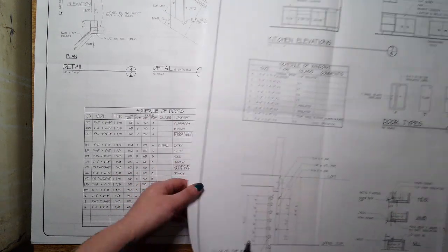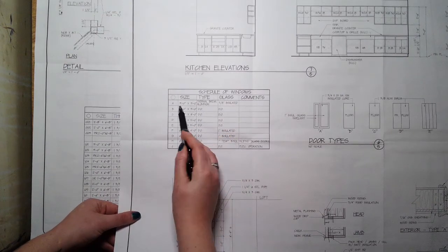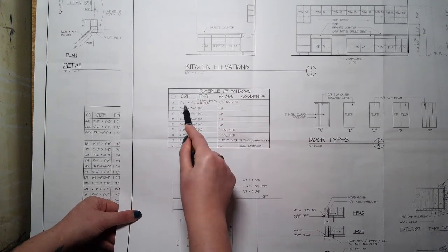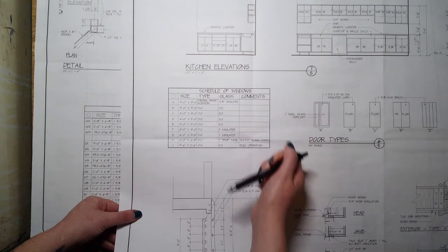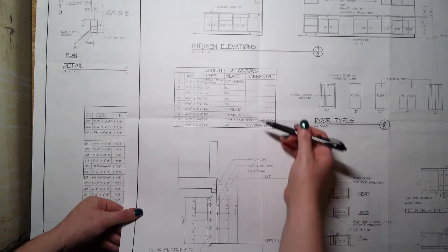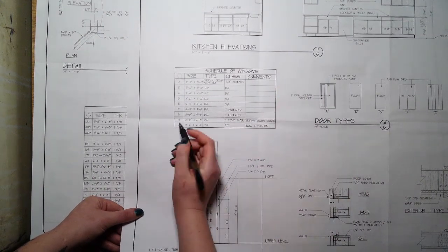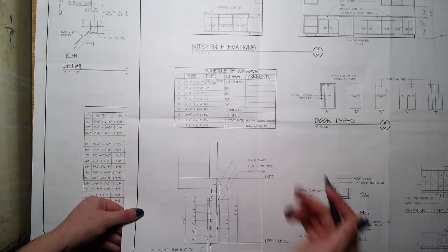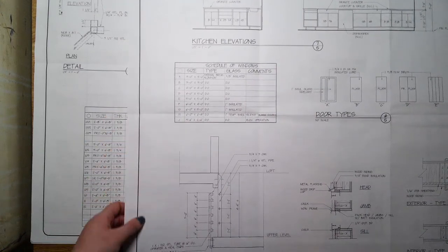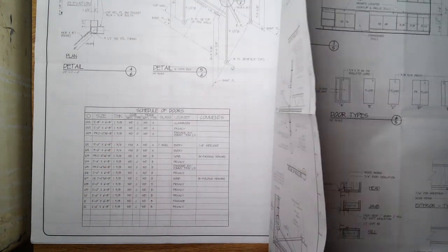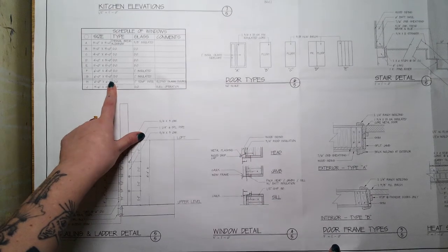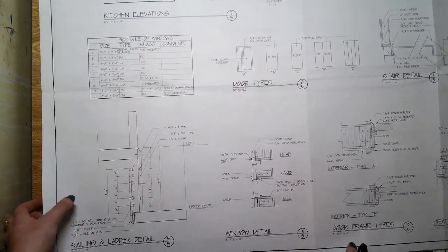And the same thing with our windows, it tells us the general size of it. So it's saying that all the windows labeled with type A have a 3 foot by 3 foot. The type of window that it might be, any type of glass that it might have, and then any comments. So for instance, this one that's window type H is actually sliding glass doors, and so it's highlighting that that one is just these sets of doors, just as a little heads up. And so you can always find that schedule. It may be located on a different set of sheets or not, but we can always find it.